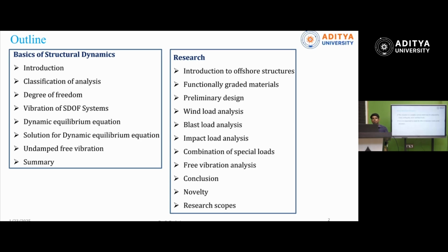So coming to this basic structural dynamics, if you see any structure in the world, it's complex in nature. So structure is made complex because of the loading conditions, particularly the dynamic loads, for example, earthquake load, wind load, wave load, impact load, hydrocarbon fire and explosion, ice loads, all these are dynamic in nature. So when the dynamic loads are acting on the structure, the behavior or the response is different. So it is important to know the response of the structure before going for a design.